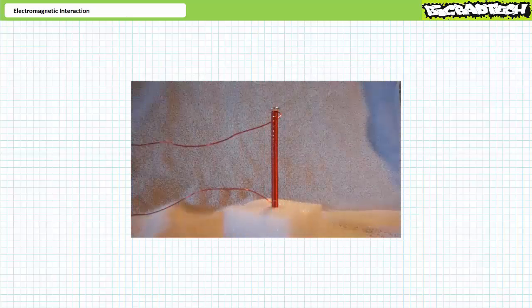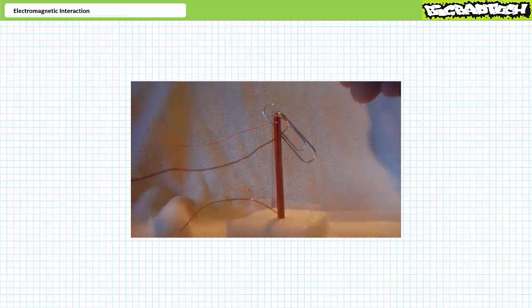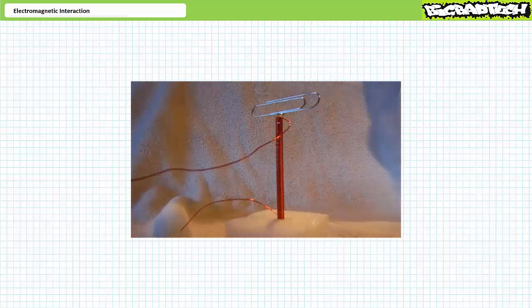Consider a coil of wire covered with a thin resin insulator wrapped around an iron nail. The iron nail is electrically isolated from the wire. However, the permeability of the iron concentrates the lines of magnetic force better than would free space. With no current traveling through the wire, no magnetism is observed. The moment current starts flowing in the coil, magnetism is observed. When current flow stops, the magnet stops.